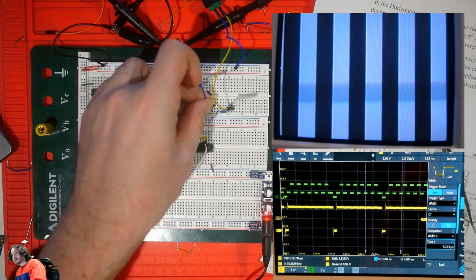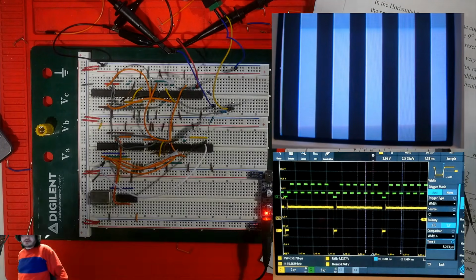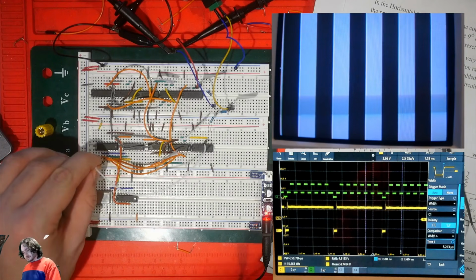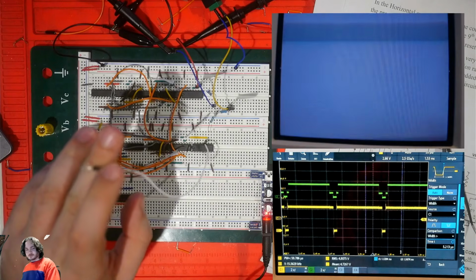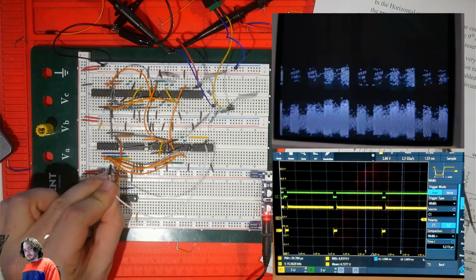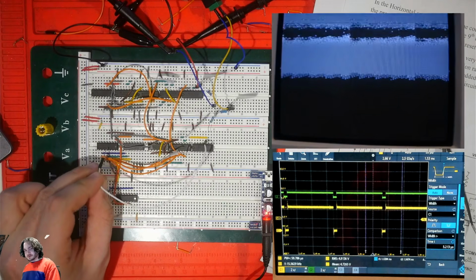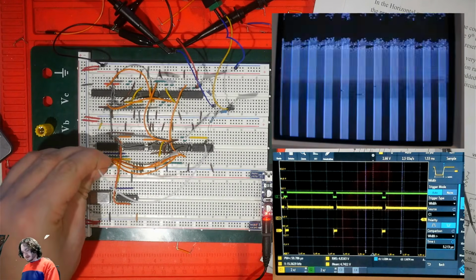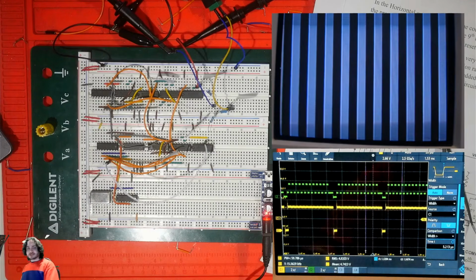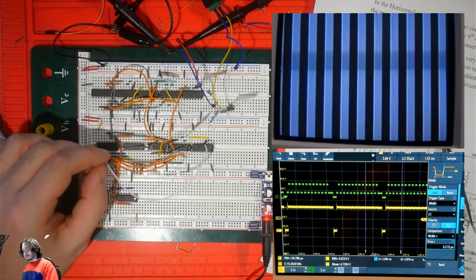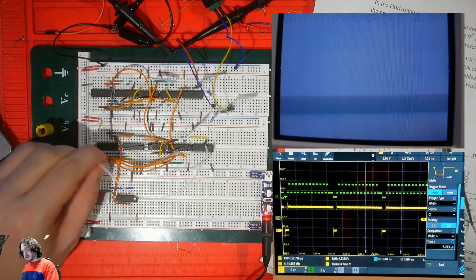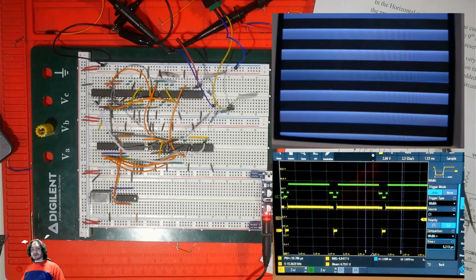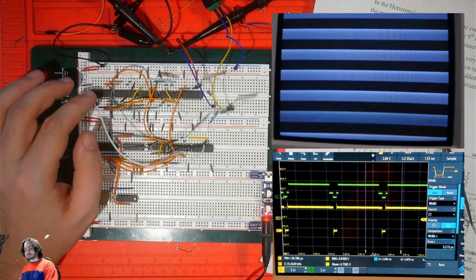So now we can monitor our video signal and our composite sync signal. So we can play with this. Right now I can hook this lead to either bits of the horizontal counter or the vertical counter. If I do the horizontal counter, the signal alternates up and down as it scans across the line, which means vertical stripes. Or we can alternate the signal for different scan lines entirely, resulting in horizontal stripes.